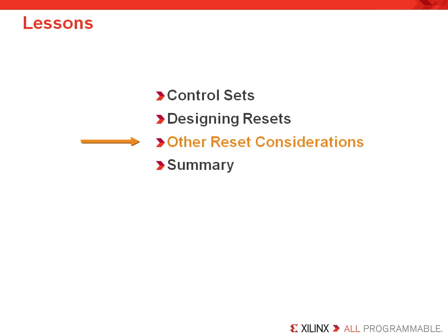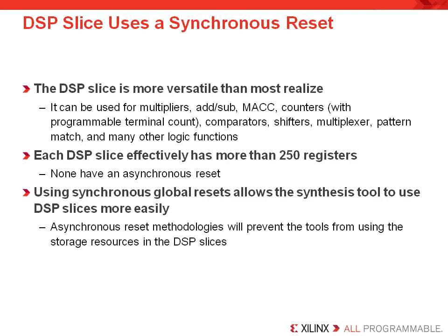Now let's take a few seconds and look at other reset considerations before doing a summary. It's very important to remember that one of the biggest reasons to use a synchronous reset is that certain dedicated hardware resources simply don't support an asynchronous reset. So if you code with an asynchronous reset, you may not be able to infer the best device resources. For example, to infer the DSP resource will require a synchronous reset to be coded.